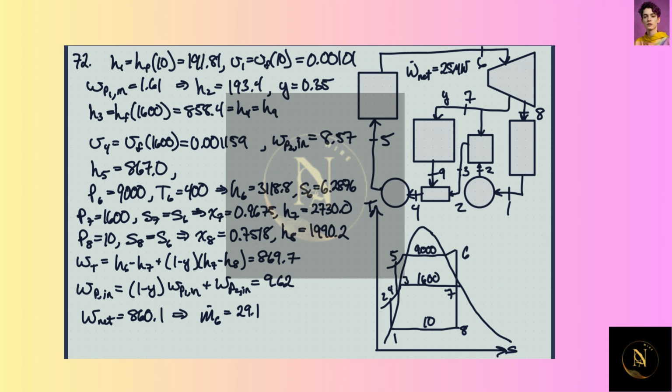I should actually put that over here, to indicate that. And then the rest, the 65%, continues on through the turbine. So again, we put some heat flow in, out, out, out. And then we just have heat exchange here in the feedwater heater. It is an open feedwater heater.